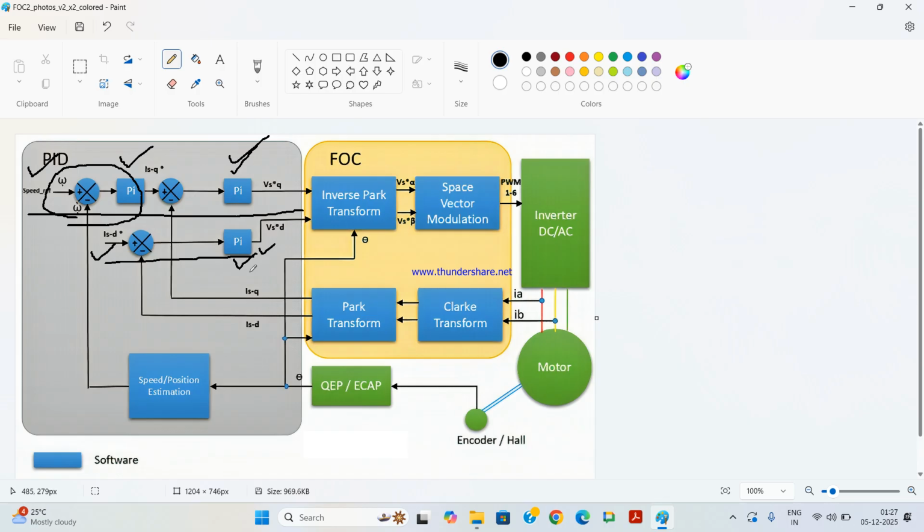Now another problem is, RPM, flow, heat, temperature, all these things are very slow processes. That means, say suddenly in a room, if I increase the enthalpy in an impulsive manner, the temperature will not increase that much faster. It will take some time. Similarly, if you increase the RPM of a pump, the increased flow will not reflect immediately. It will take some time because it's a very slow process.